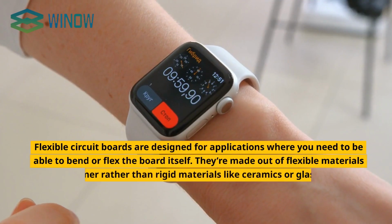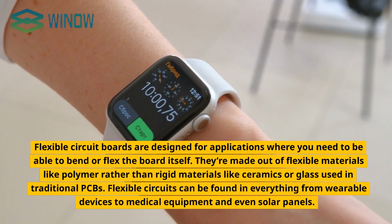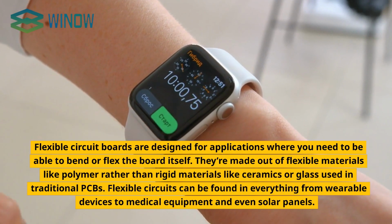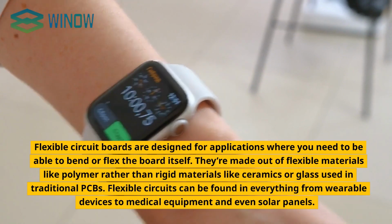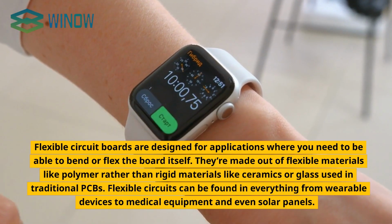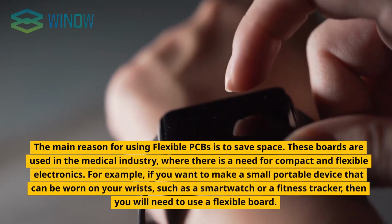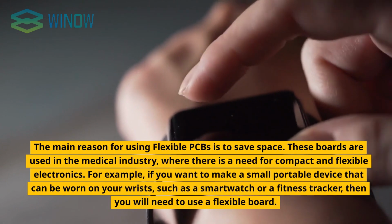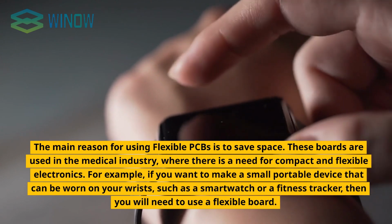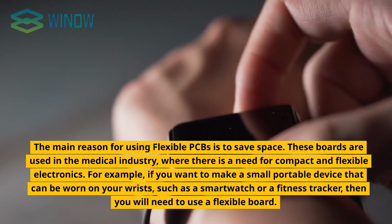Why do some electronics have flexible PCBs? Flexible circuit boards are designed for applications where you need to be able to bend or flex the board itself. They're made out of flexible materials like polymer rather than rigid materials like ceramics or glass used in traditional PCBs. Flexible circuits can be found in everything from wearable devices to medical equipment and even solar panels. The main reason for using flexible PCBs is to save space. These boards are used in the medical industry, where there is a need for compact and flexible electronics. For example, if you want to make a small portable device that can be worn on your wrists, such as a smartwatch or a fitness tracker, then you will need to use a flexible board.